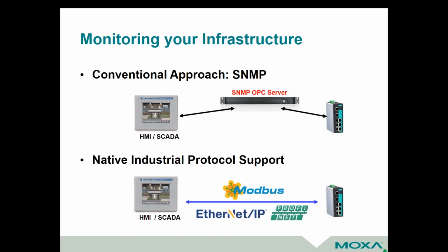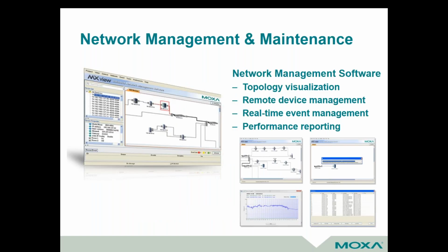And that could be simply something as an overload condition that caused a breaker to trip and caused a VFD to go offline, and when the VFD goes offline, losing that link status on the switch. So some really cool stuff here, and I hope if you're not using that, you'll think about that.